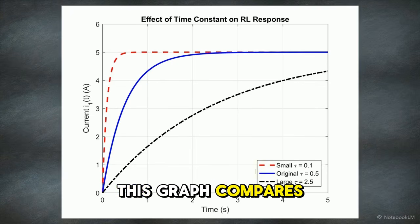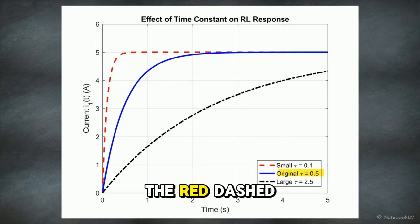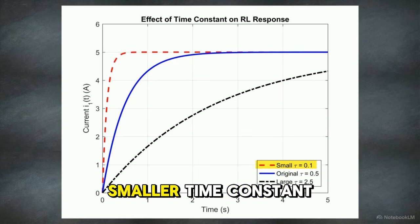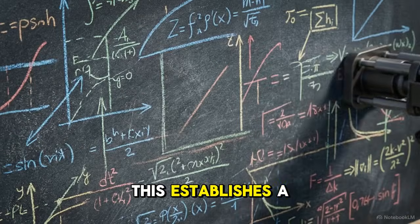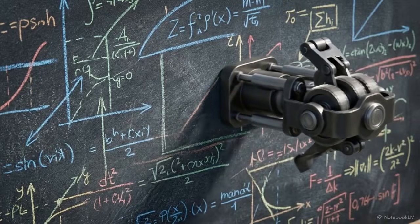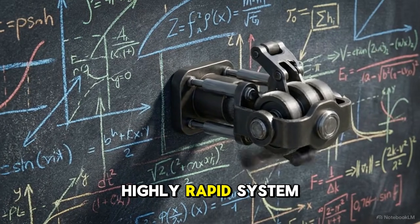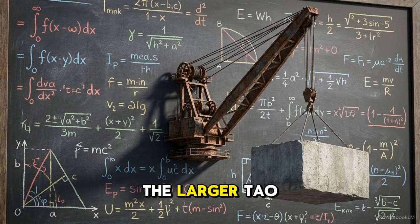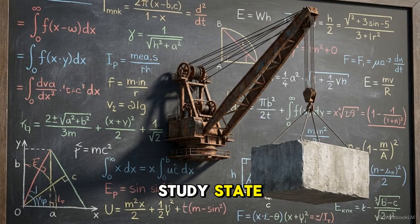This graph compares our original response against two variations of the same system. The red dashed line represents a smaller time constant of 0.1 seconds, while the black line shows a larger time constant of 2.5 seconds. This establishes a rigid engineering rule. A smaller tau indicates low inertia, resulting in a highly rapid system reaction. A larger tau means high inertia, producing a sluggish climb to the steady state.